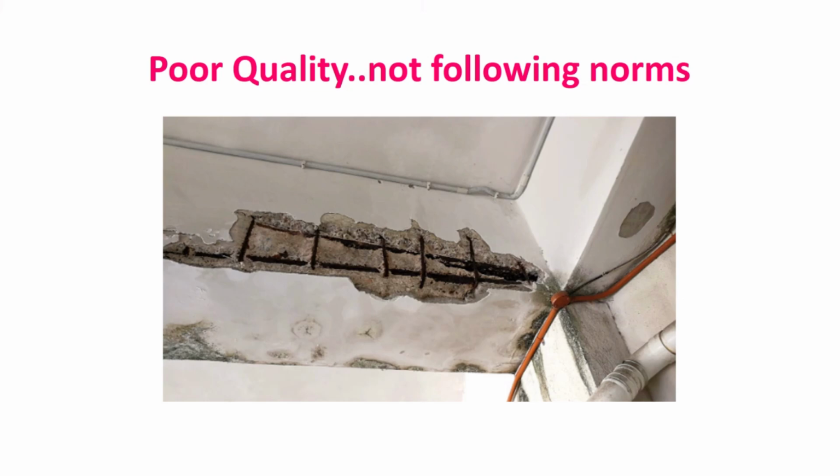We normally go for M20 or M25. But please refer to those codal requirements, so that in case it is a very severe requirement, possibly the minimum grade of concrete may be M30. So I will be required to use those tables. I suppose everybody agrees to this.